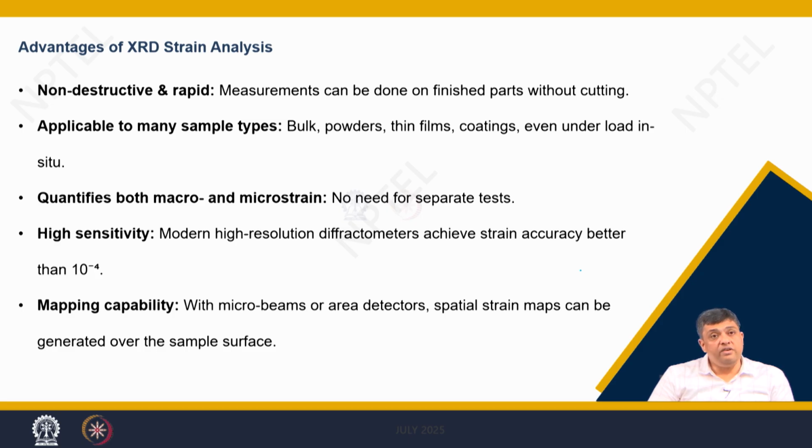You can quantify both macro as well as micro strain. You do not need to carry out separate tests. The modern high resolution diffractometers are highly sensitive, and you can achieve strain accuracies of 10 raised to minus 4 or even higher.